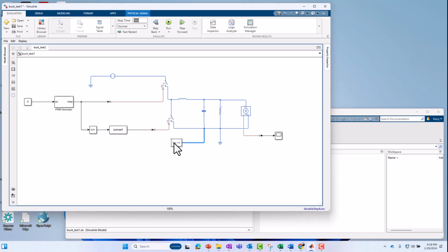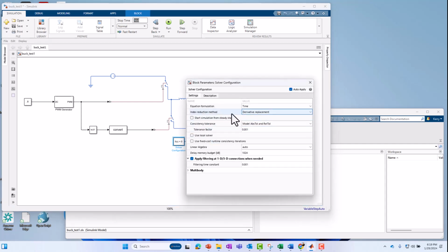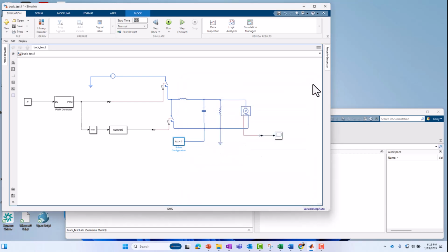This block, by the way, doesn't simulate, it doesn't consume voltage or current, it doesn't generate a voltage or current. It's simply there to tell Simulink that it's Simscape and it could use its own particular solver settings. In this case, I'm going to be using the Simulink global solver to simulate the Simscape circuit, but you could click here and use the local solver with a particular sample time. I'm not doing that here yet. But it still needs to be there in any case. It's a matter of logistics and infrastructure, just a checkpoint.